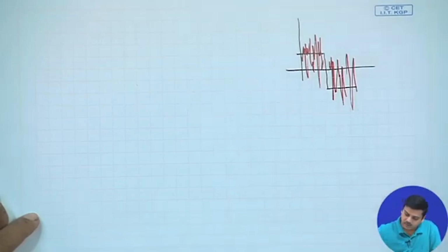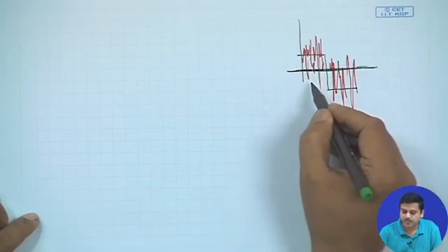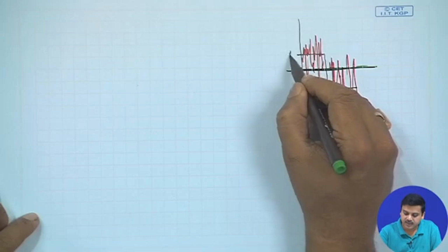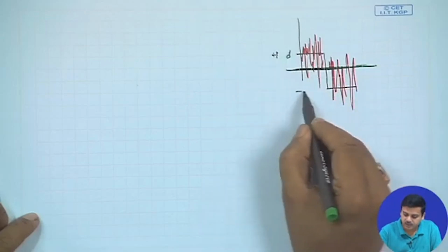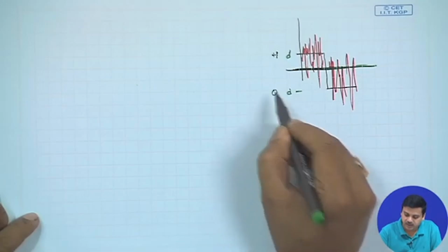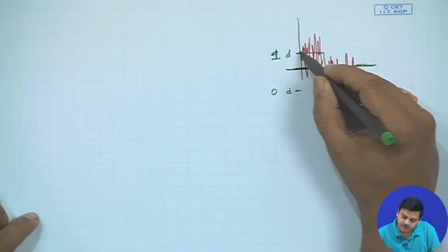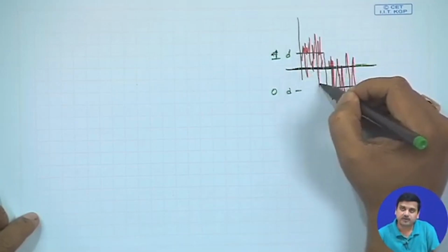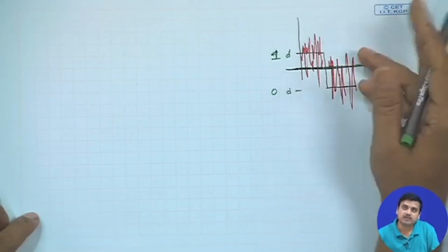Whenever the signal crosses this threshold on the upward side, you would identify it as D, let us say a 1, and minus D would mean a 0. Because of noise, if instead of detecting it at this level, I detect a negative value, then instead of 1 I would make a decision of 0, and vice versa.